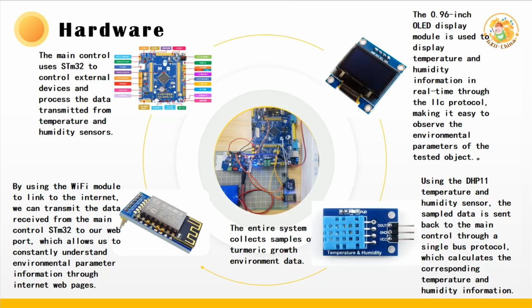This project has designed a temperature and humidity Internet of Things monitoring system based on STM32 single-chip microcomputer, which is divided into 2 parts, the sending end and the receiving end. OLED displays. DHT11 collects temperature and humidity, and the Wi-Fi module delivers the information to the server. The receiving end is displayed in the form of a web page. The web page interface includes the address port of the server, the subject of the subscription, the data read, the relevant commands sent, and so on.